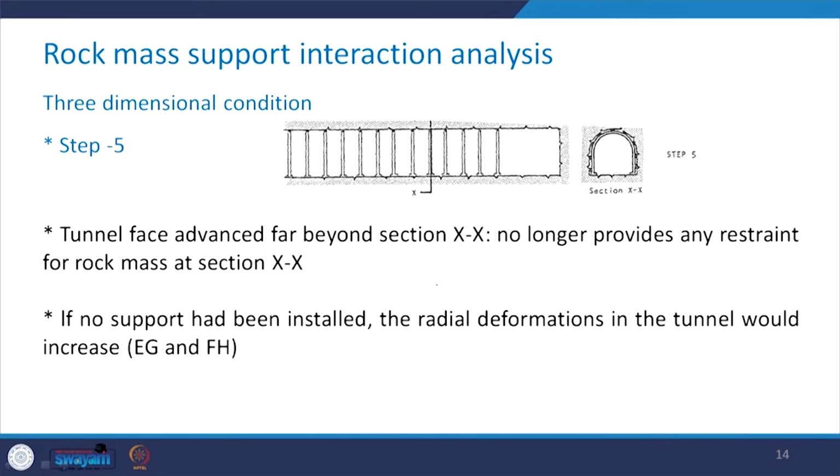Coming to the next step, which is step number 5, in this case, beyond this section XX, the support system has been installed and the tunnel face has been further advanced, and now this face is much farther than this section XX.